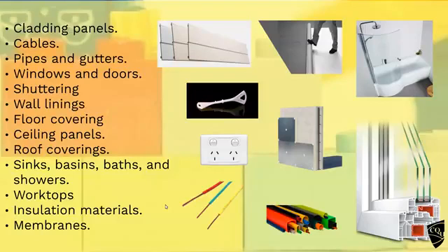It can be a damp proof course barrier underneath a solid floor, or in a leaf of a wall. There's loads of uses of those. And of course there's the obvious bits not mentioned there, so electrical outlets and fittings and fixtures, okay? That's a wall tie. That would be between here, between the two, cavity here, tying these two together. You get different types of wall tie plastic.